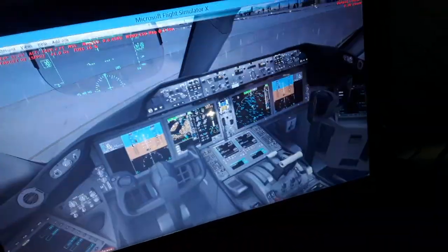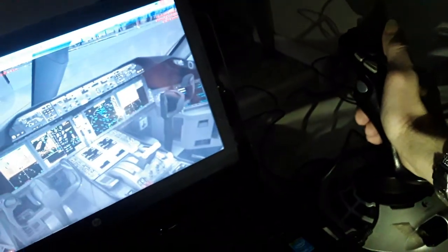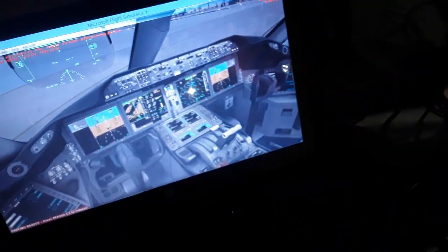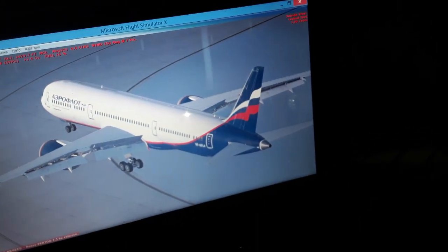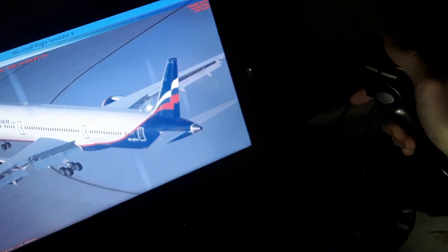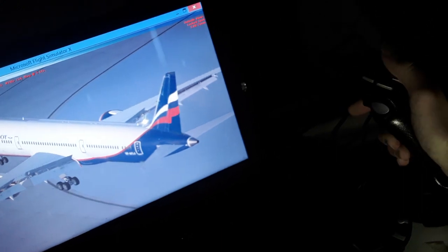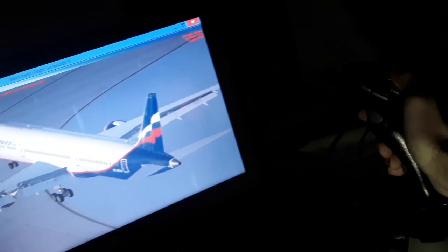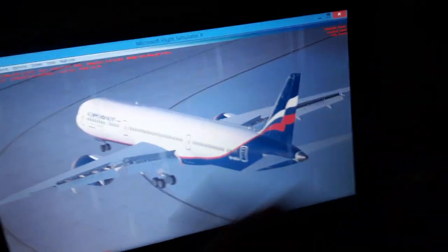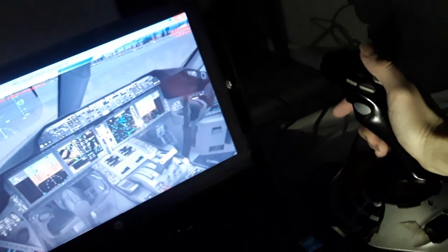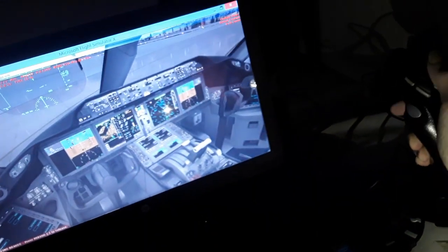Or you can use the rudder pedals, they're interconnected many times, or you can disconnect. After 45 knots, the rudder is aerodynamically effective, and the nose wheel deflection is decreasing to 7.5, 7.6 degrees until 70 knots takeoff speed. We have only the rudder aerodynamically effective, and we lose the tiller.